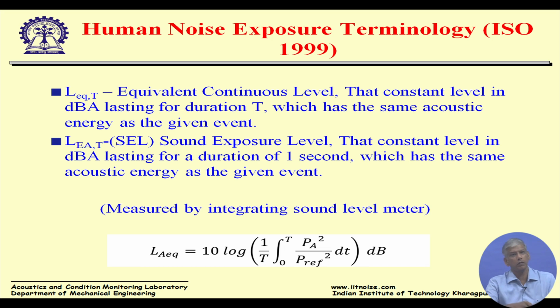So, you have to put your sound level meter on for 5 hours and integrate and so on. Nowadays in the airports, you will see continuous noise monitoring terminals, NMTs. You can define a period, and then they will data log it, find out a single number, and even store it in a database. Right now as I speak, it is being installed in Bombay Airport, and you have NMTs close to the runways, so that people are recording these values with traffic density, what is the level, how high, and so on.